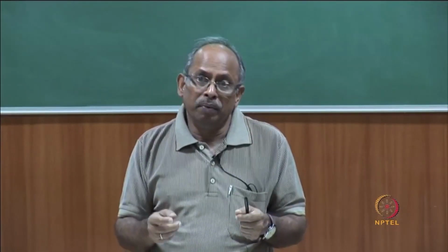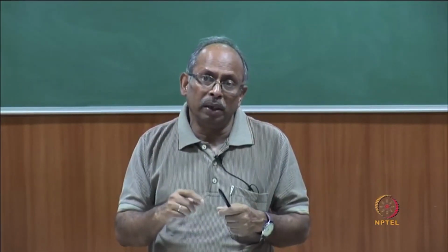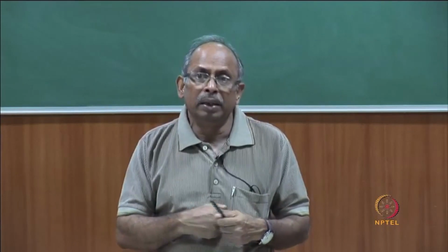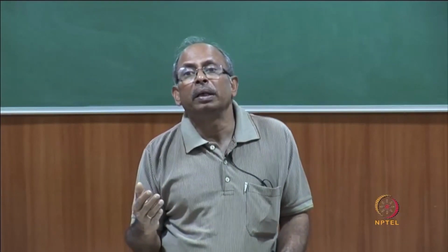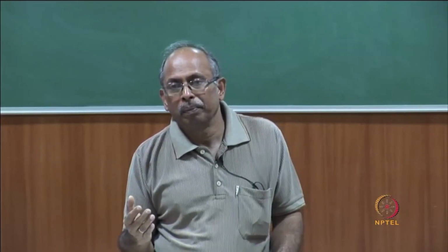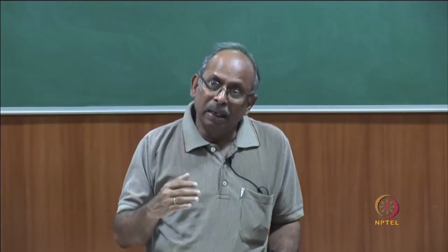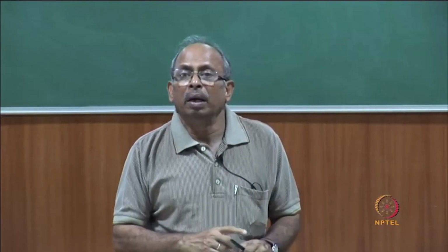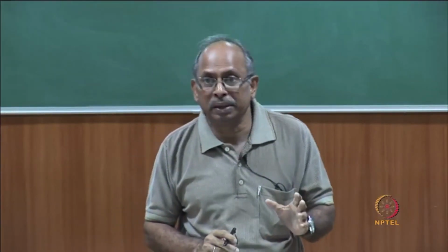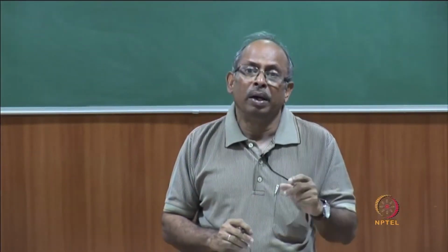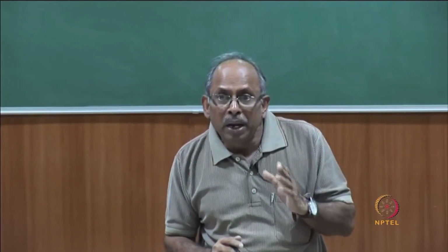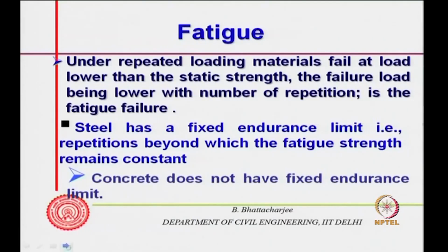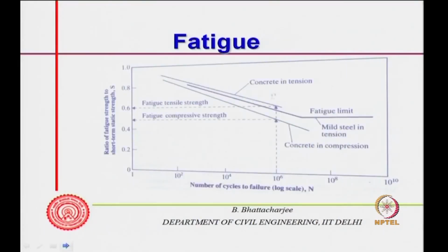Now, if you lower the load, if you lower the range in which you are operating, then it will take more number of cycles. So, the number of cycles is a function of the level of the stress reversal. Now, endurance limit is defined in this manner. It is much better to define this by looking at a diagram.